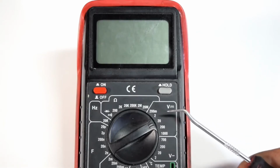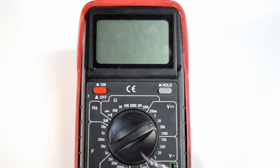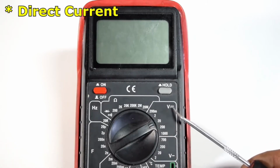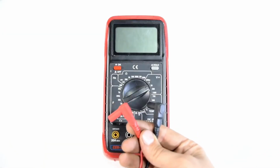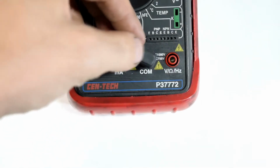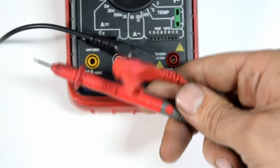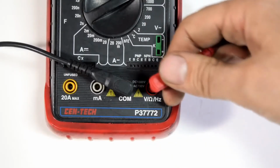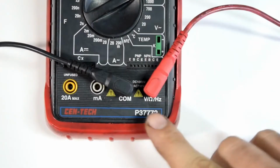When you're using the multimeter to measure DC voltage, you need to set your dial to this setting, where you get a V for voltage and the straight and dotted line for direct voltage. Next, you need to make sure your test leads are in the right location. Your ground or common test lead is always going to go right here where it says COM. But the red test lead is the one you're going to be switching around based on what you're measuring.